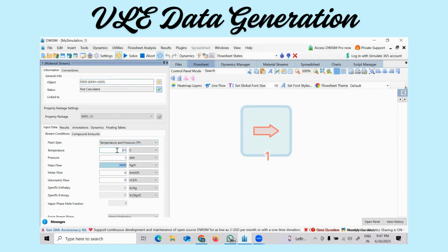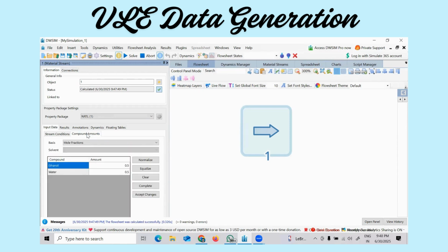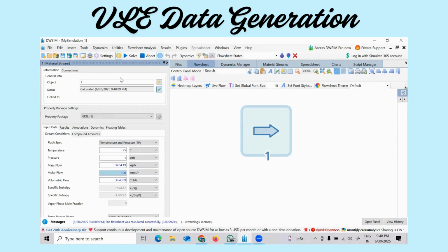Now the temperature which is being taken is 25 degrees centigrade and pressure is 1 atmosphere. And let us take the molar flow rate as 100 kilomoles per hour. Okay. And if I press enter, then automatically the other conditions are calculated. See, mass flow rate is calculated, and then volumetric flow rate, specific enthalpy, specific entropy, all things are calculated, but we need to understand what is a binary mixture. So this is 0.5, 0.5 by default. So if I say accept changes, and then go to the conditions here, the color of the stream has already changed from red to blue. Now, if I say solve again, it is solved.